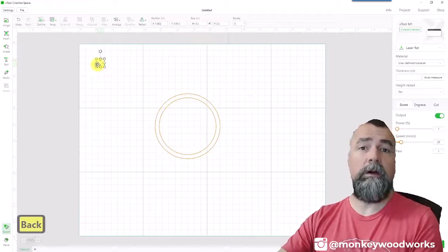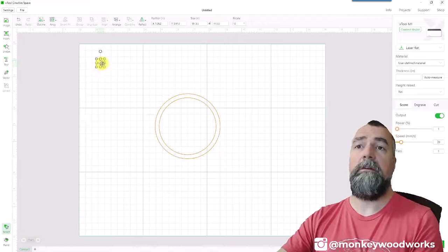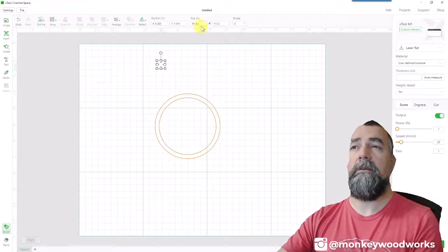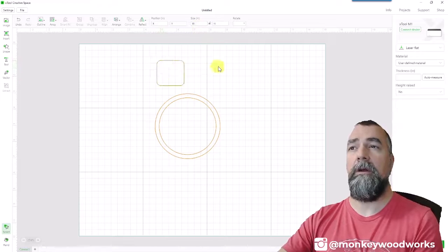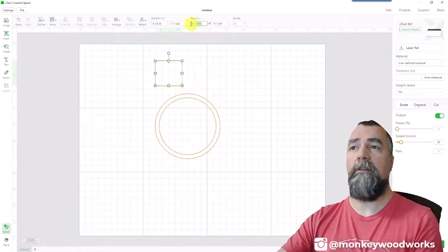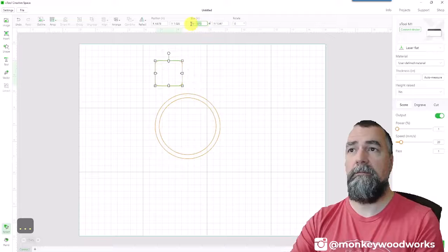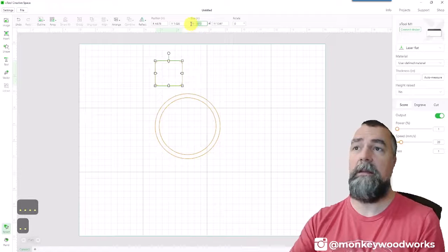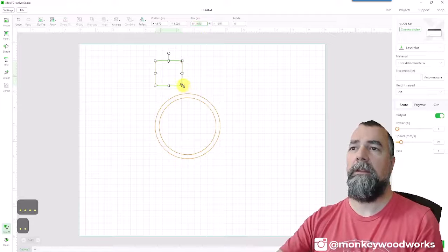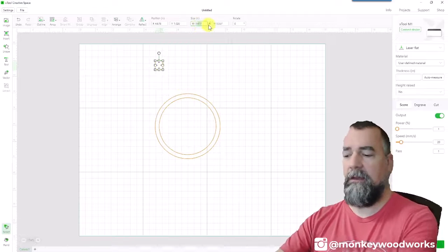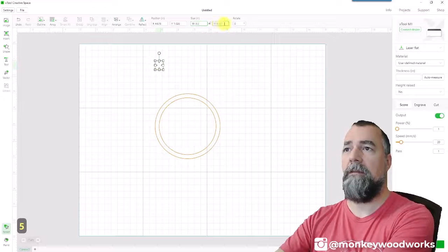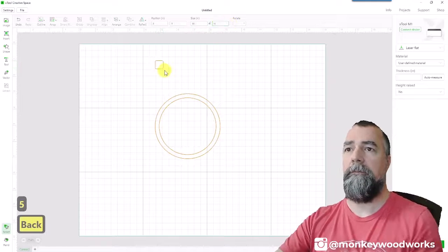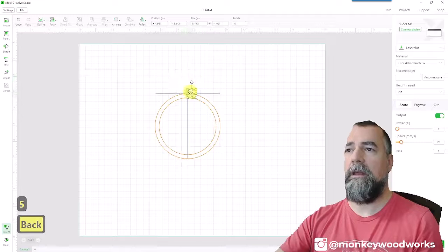That is a small bug in XCS that they're actually working on. So yeah, you can't go from a big number and just override that and just say I want to make it 0.5. The point doesn't work. So you see, I'm pressing down there in the bottom right. It's not typing it. So, to get around that, you can drag it and get it below that mark, and now I can actually adjust it. So let me make it 0.5 on both sides, and I'm going to move it in place.